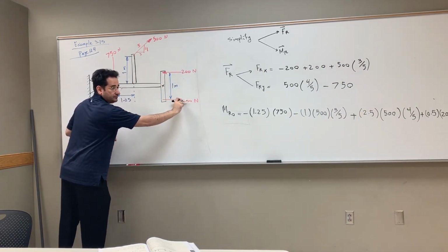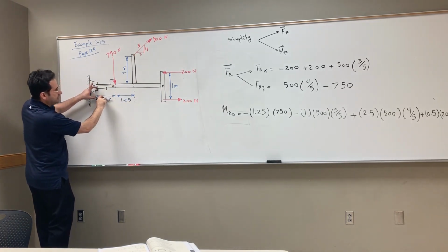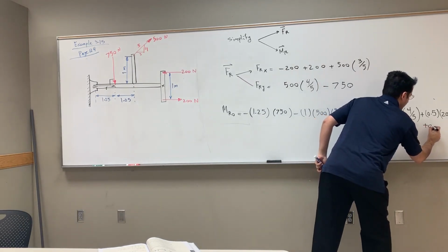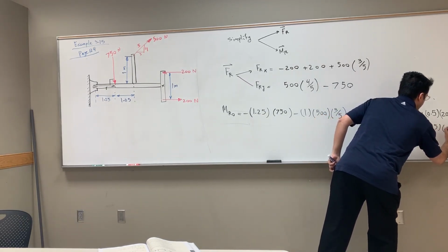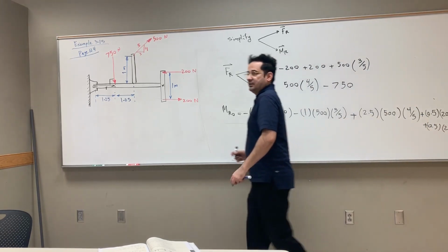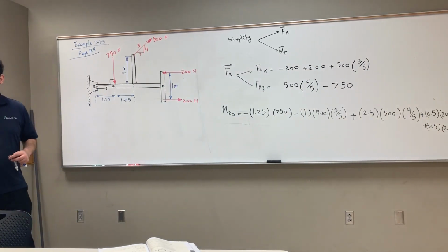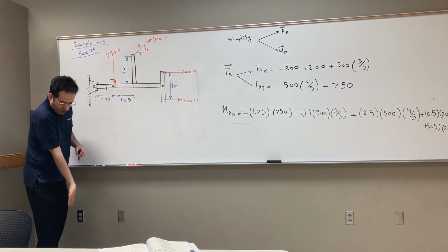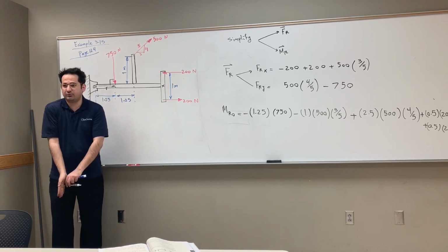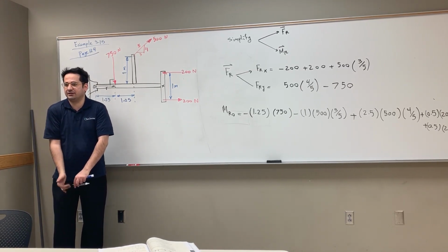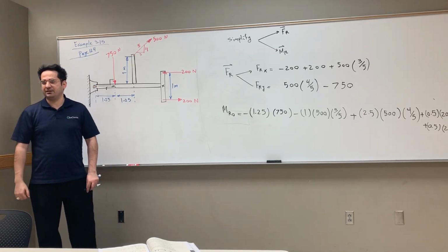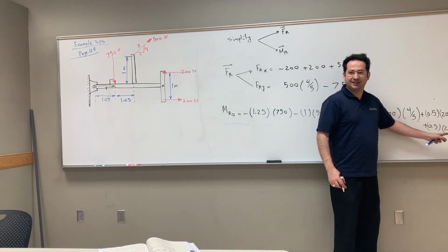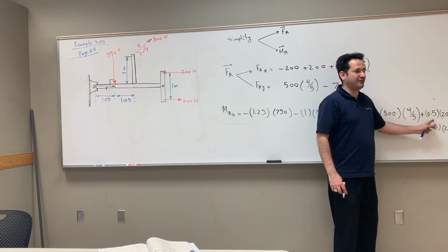Now go to this one. Move it. Where should I move it? Back. So what's the moment arm? 0.5. 0.5 times 200. Positive or negative? Positive. That's the point. Take your right hand. This is your R from here to here. Goes to R, then the palm would show the force 200, and then the thumb is positive K. So as you can see here, if you factor out the 200 Newton, half plus half is 1.